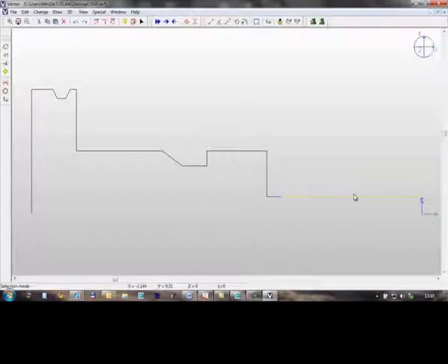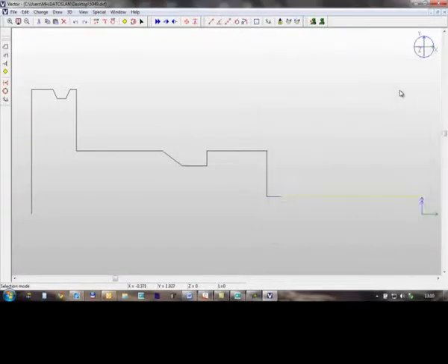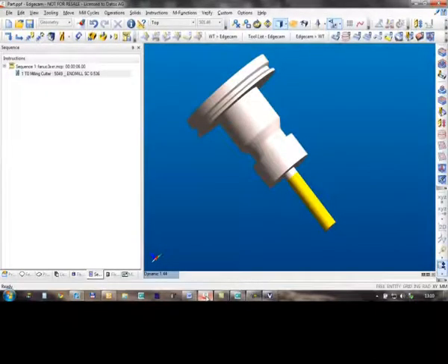We create the contour with the cutting layer, the non-cutting layer, cut, no cut, and shank with the 0 point at the tip. Now this contour is imported into EdgeCam and rotated into a 3D model with a cutting and a non-cutting portion to it.